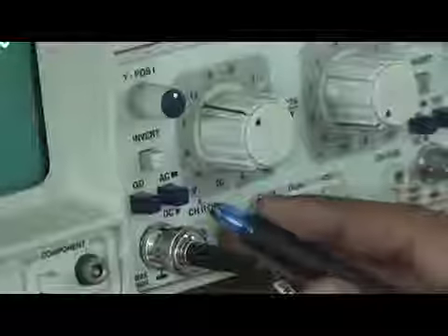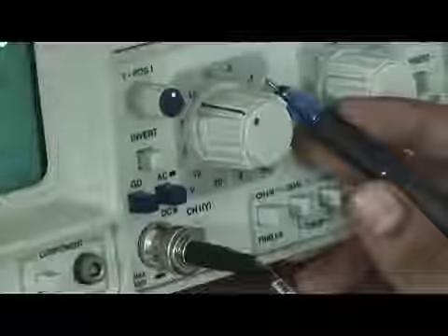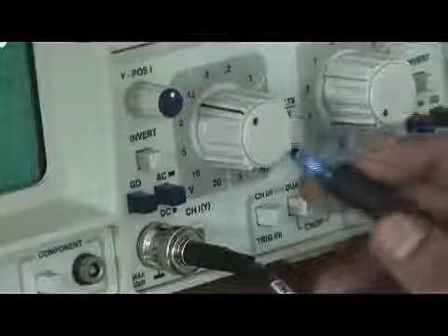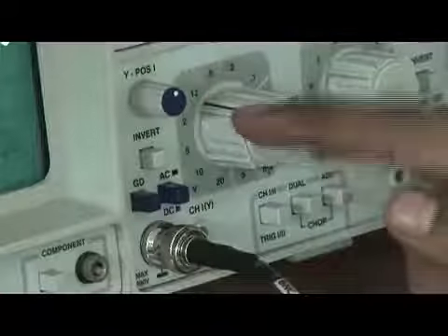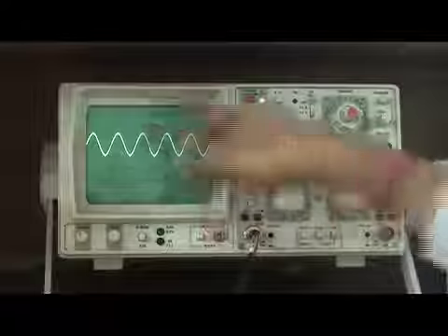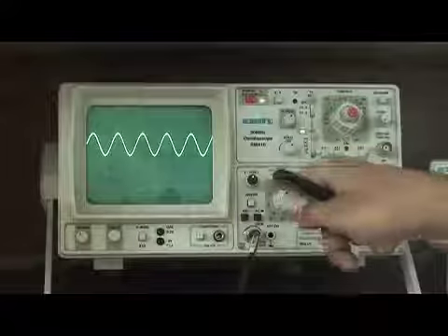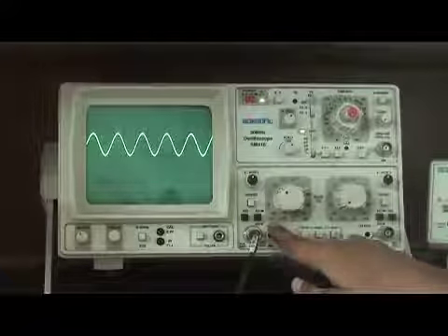There is only one unit called V, meaning volts. From this gap to this gap, there are various numerical values, but there is one unit called millivolts. So whenever this knob lies in this range, the unit will be millivolts. When this knob lies in this range, the unit will be volts. So 1.9 blocks into 1 gives 1.9 volts.